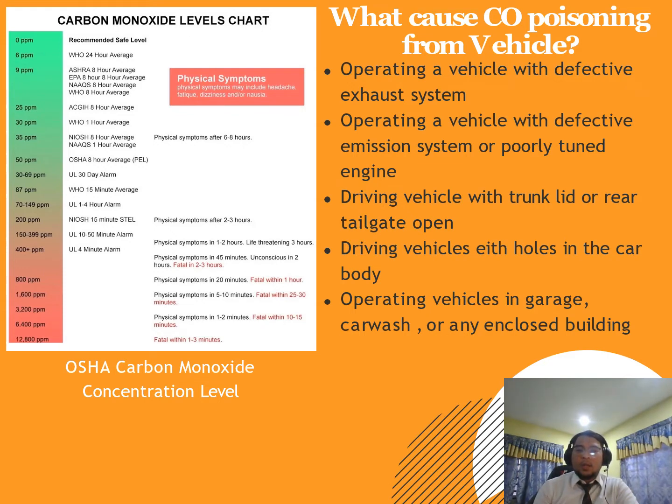The table tabulates the concentration level as stated by the Occupational Safety and Health Administration. From 0 to 200 ppm is the safe level and 200 until 800 will cause physical symptoms. 800 and above is dangerous, CO exposure will lead to fatality.